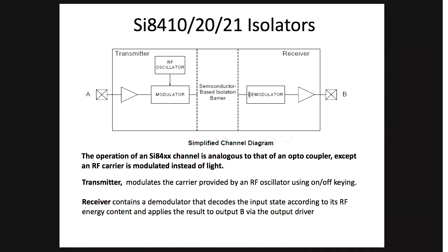That's the reason for RF. You might be thinking, why are these guys crazy, replacing LED with RF? Why do they want to complicate? Because when you have RF, you can increase the frequency of the signal. So their advantage is they can isolate from DC to RF, DC to very high frequency.